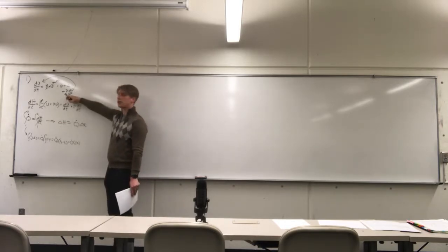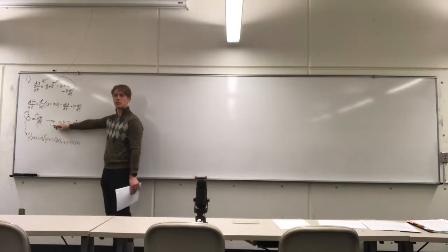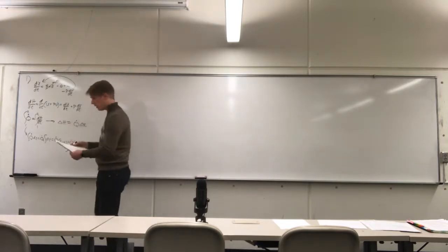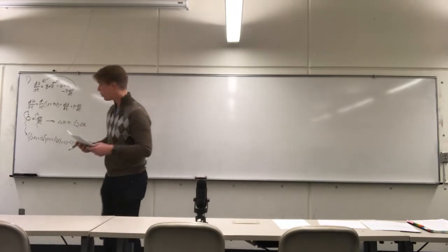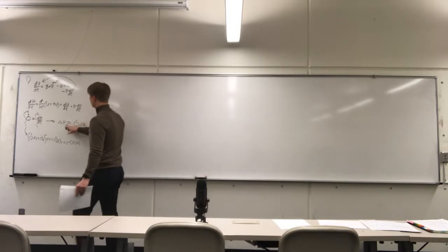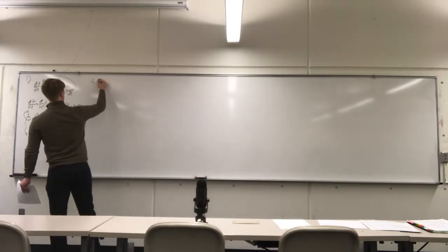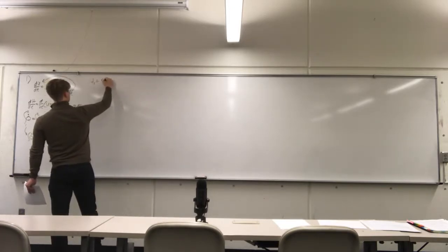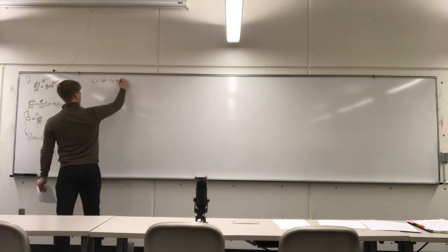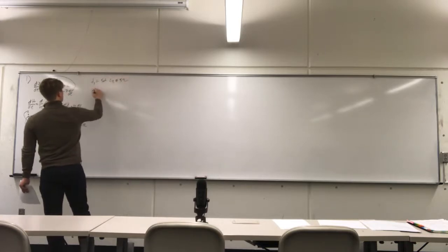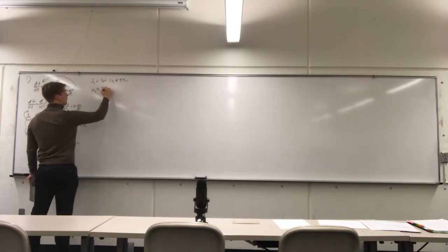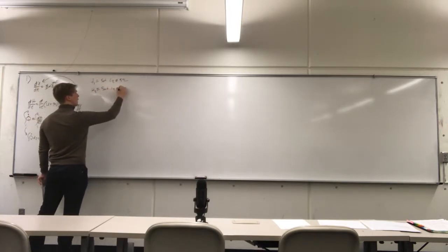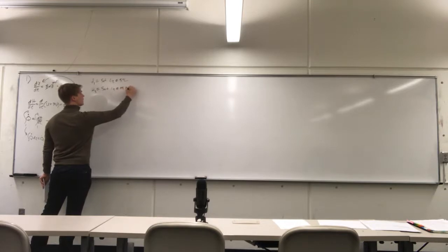Consequently, if you say that the work is 0, then this would be delta U, and that's where a lot of mistakes were made. But ultimately the answers were, what were the answers? So we actually just had to look these values up. Enthalpy of state 1 was a saturated liquid at 5 degrees Celsius. Enthalpy of state 2 for part A was a saturated liquid at 75 kilopascals.